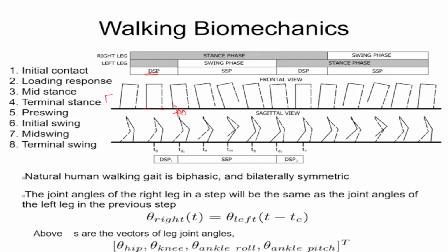So this is the front view and that's the side view. If you look at both the feet, this is the rear foot. It has bent on one side, and in single support phase, this foot is coming forward like this. So this foot is in the air now. You can see it's in the air. This is the trajectory it is taking. And all the while in single support phase, the robot is bent at that constant angle. So this is all single support phase, from here to here, and then it becomes double support phase